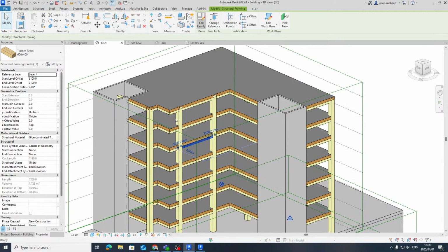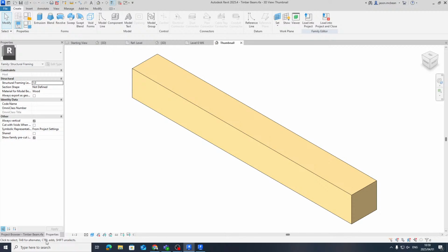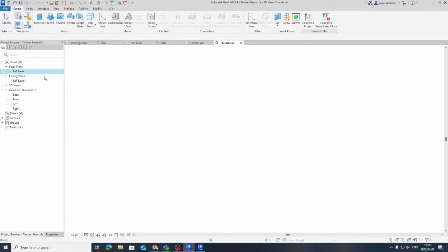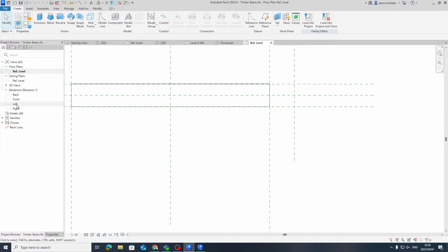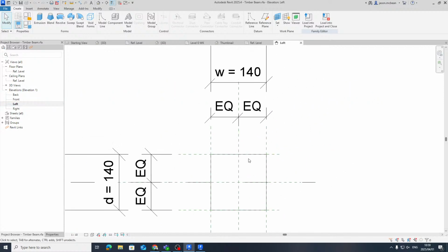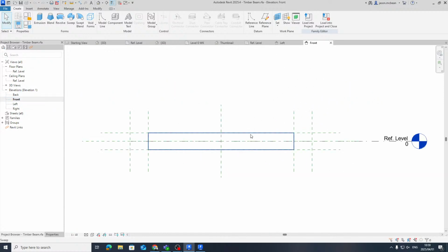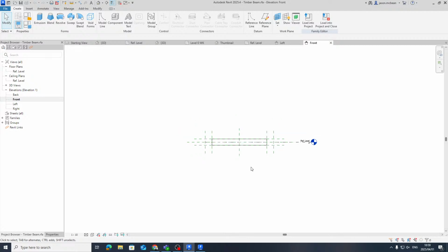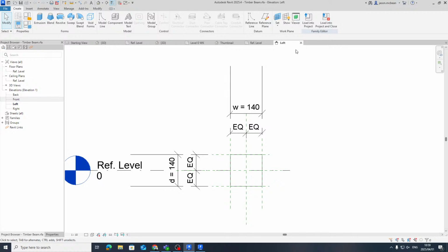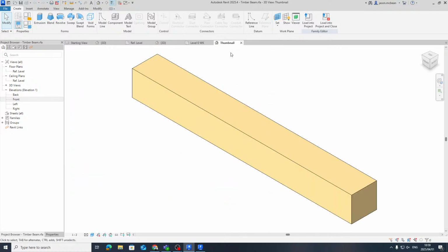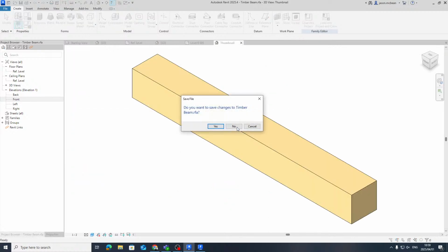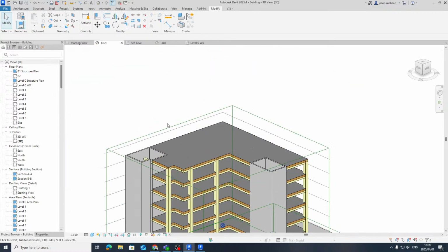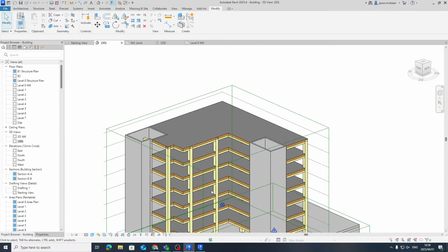To make these timber beams correctly, these are all families that have to be set up correctly, and they have got lots of parameters. You'll see if you go to left, right, these beams are driven by parameters. So to model this stuff just on the fly, it's almost impossible in Revit. Okay, there's a lot of work that goes into these models to make them work correctly. Yes, once you've got the library working, it's very quick. But to get to that point, it's weeks of work.